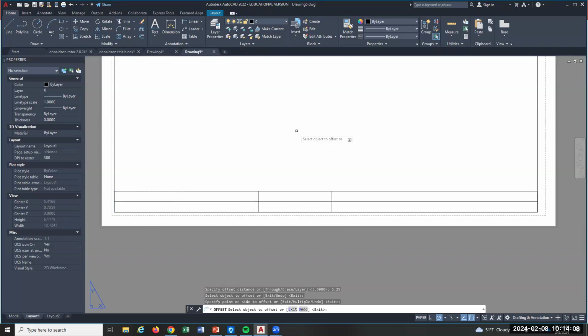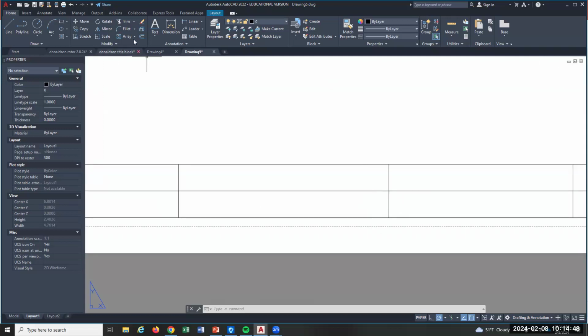I'm just offsetting, yeah? Space bar brings it back. 7.25. And 9. Everyone see what I'm doing? Yeah, pretty handy, huh? That was a lot better than trying to figure out where to put things, just offset things at distances. I offset long lines, short lines, all kinds of things because it's super easy to trim, right? One second. So this one is not supposed to go the whole way, right? So I want to trim that part off. The trim command is good for that.